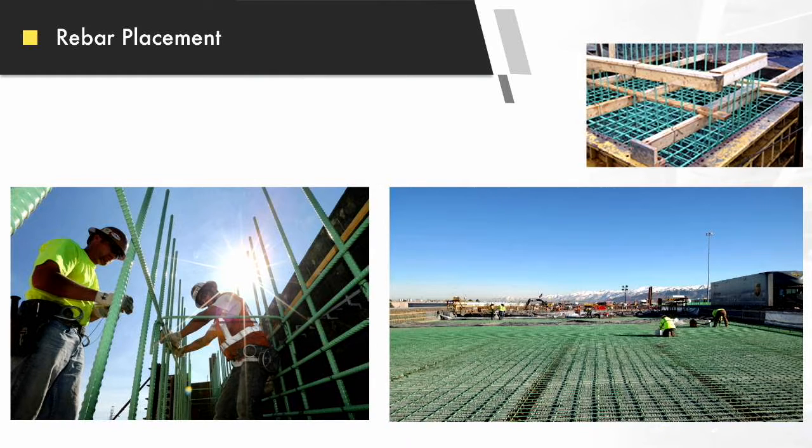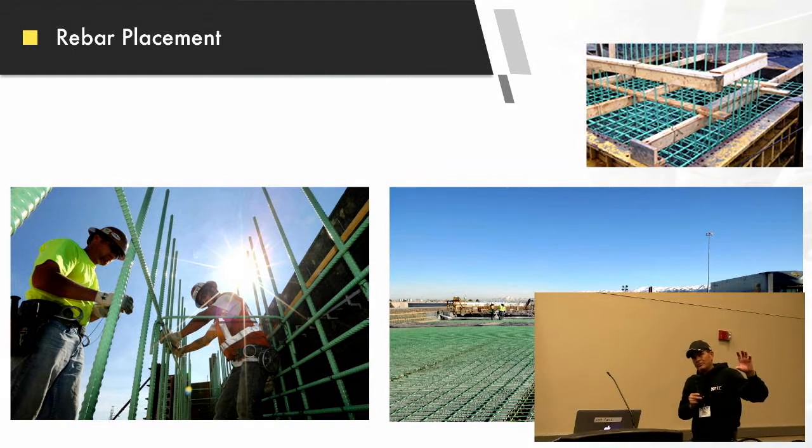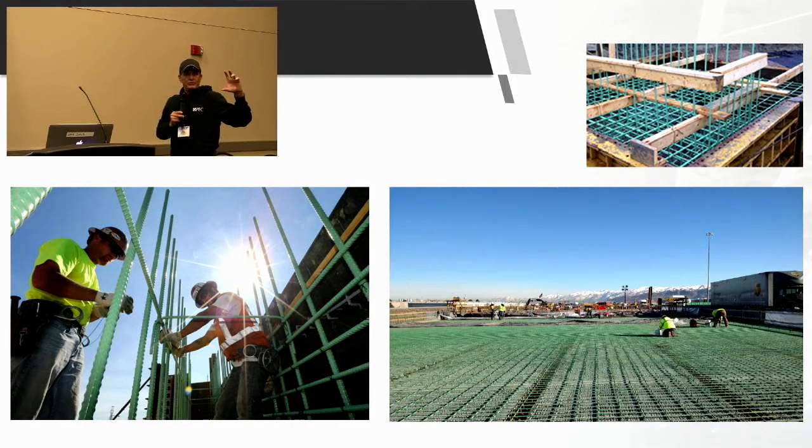On this footing over here with your uprights coming out, they've got all those secured so that as you're placing, those things aren't going to be moving around. They're in the proper location. This is really important, like on bent caps that you're doing a bent diaphragm right on top of your bent cap, where your girders are coming in between some uprights, so you're not having to go in and bend your uprights, cut them, redowel them, because again, it's just not needed.